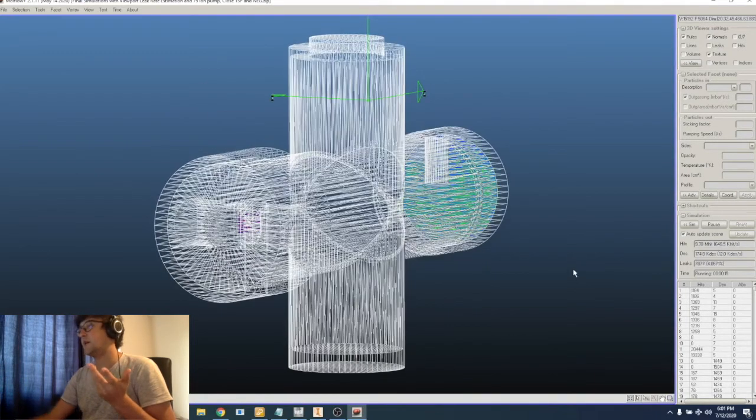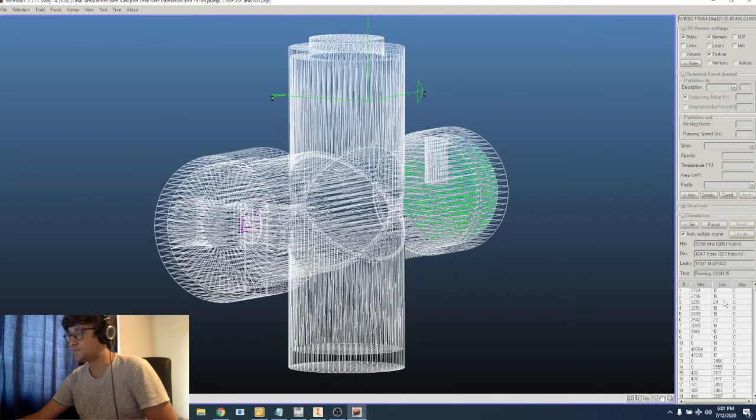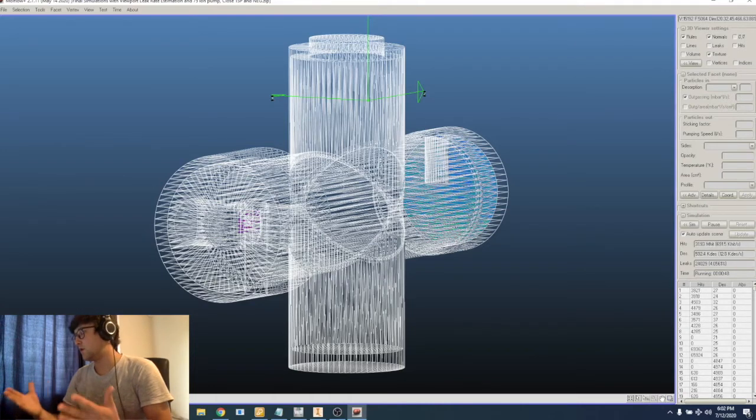Again, those outgassing rates are going to be your limiting factor, and they limit the certainty in your simulation. Once you've assigned the desorption and the sticking factors for basically all of the facets in your system, you can start the simulation. I don't have a specific way of calculating how well it's converged, I just run it generally for a few hours, but it does converge pretty quickly, so it shouldn't take very long.